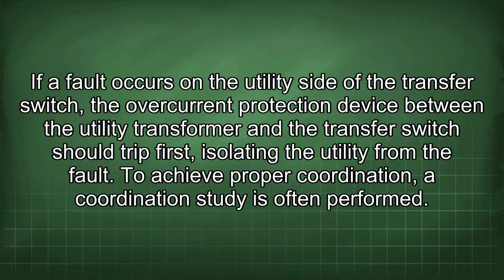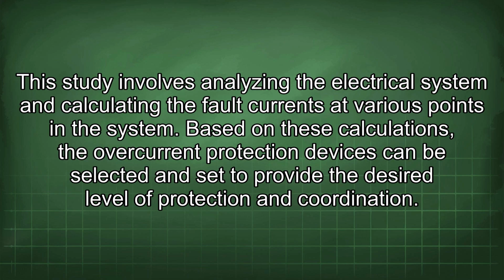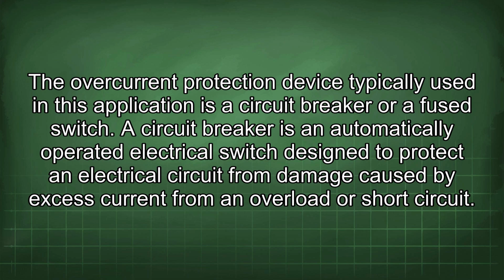To achieve proper coordination, a coordination study is often performed. This study involves analyzing the electrical system and calculating the fault currents at various points in the system. Based on these calculations, the overcurrent protection devices can be selected and set to provide the desired level of protection and coordination. The overcurrent protection device typically used in this application is a circuit breaker or a fuse switch.